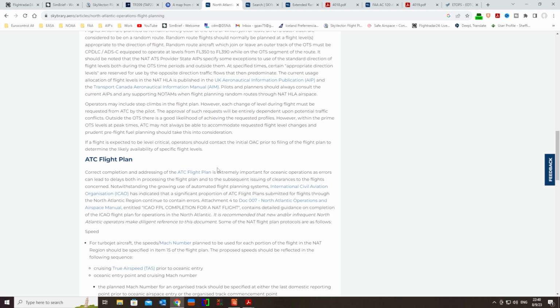But we need to know how to cross it and how to properly place our airports around the map, because when I did the example, I realized that Simbrief is always considering 180, and even if you click on the 120 minute ETOPS requirement, it doesn't pick up the correct suitable airports for your flight.